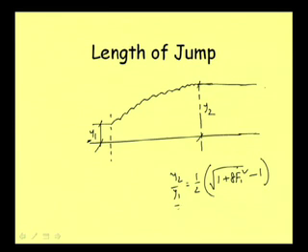If you remember, in this formula we are neglecting several points: first, the slope of the channel is neglected and considered to have no effect, and then the frictional resistance offered by the channel is also not considered here.